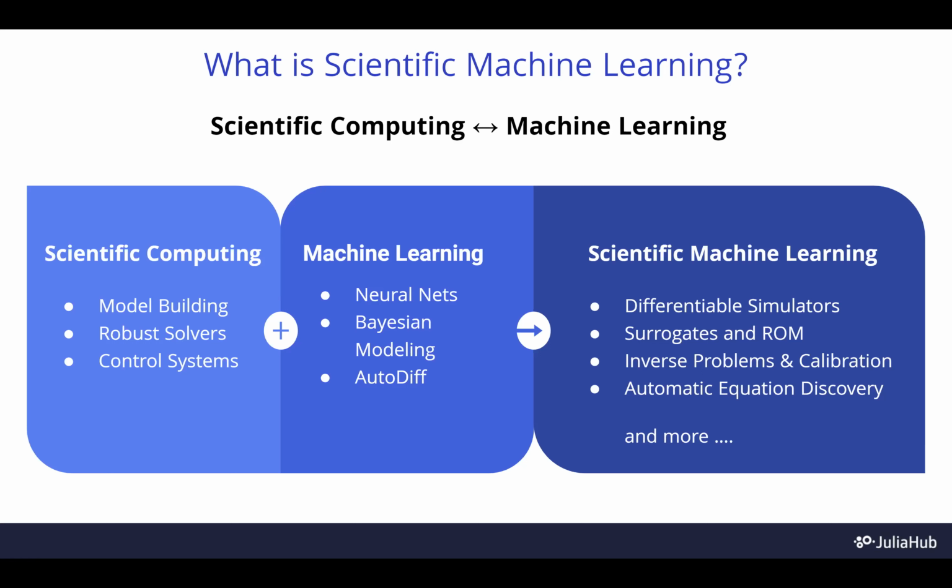So there's an aspect there that involves building models, right? And of course these are derived from the physics and are set up in a programming language or an environment, right? And once you have this model built, you then think about discretizing and then solving this model. So in the fluid dynamics case, you would use some sort of finite volume or finite element type mesh simulation to be able to simulate this, right?